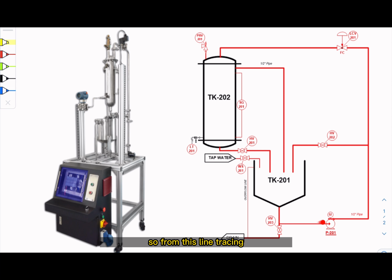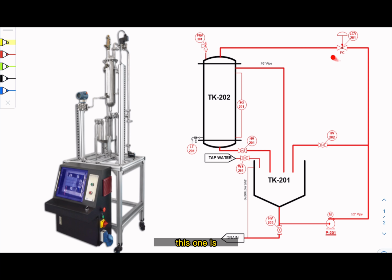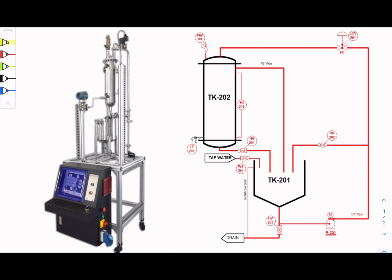From this line tracing, we can see that we have P201, which is the feed pump, and then it goes right up to the regulated valve. The label is LCV201. LCV means level control valve, and then it goes to the main process tank, TK202.